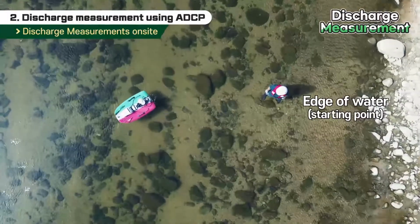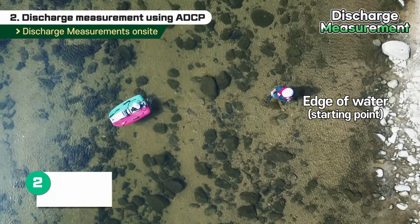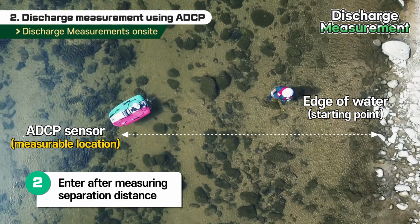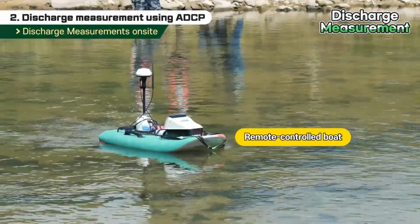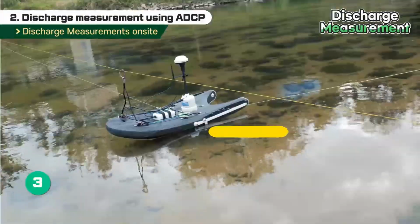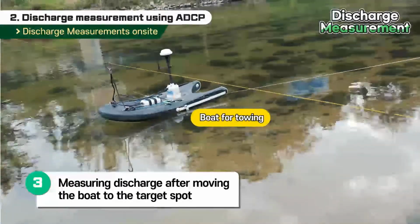First, since the edge of the water is low in depth and cannot be measured, please click Start Edge to enter the separation distance, which is from the starting point of the water edge to the measurable sensor, into the operating program. Here is an example of what the operating program looks like. After checking the distance of the installed boat and the separation distance input into the laptop's program, start measuring the discharge by moving the boat toward the target spot on the opposite side.